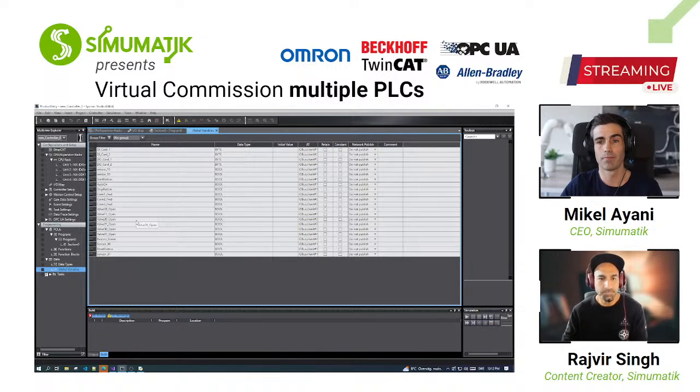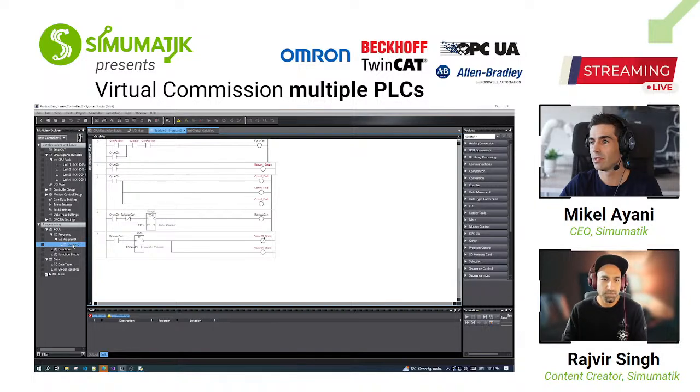I think it's quite similar to what we do in Siemens PLC as well. We just take bytes and then we take individual bits. Exactly. The difference is that we use addresses, for example, when you work with the S7 protocol and so on. Here you just use a name. Variables. So it's like OPC UA, you use the variable name.